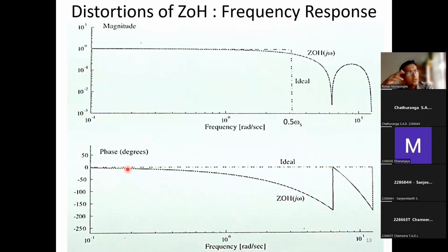Remember, back in semester 1, we decided that for every plant we need to have about 45-degree phase margin in the initial design, okay? That is why it is so important to have that much phase margin, because now in the second semester, when you convert into discrete format, you have to sacrifice some of the phase that you already retained in the continuous time control design, right?